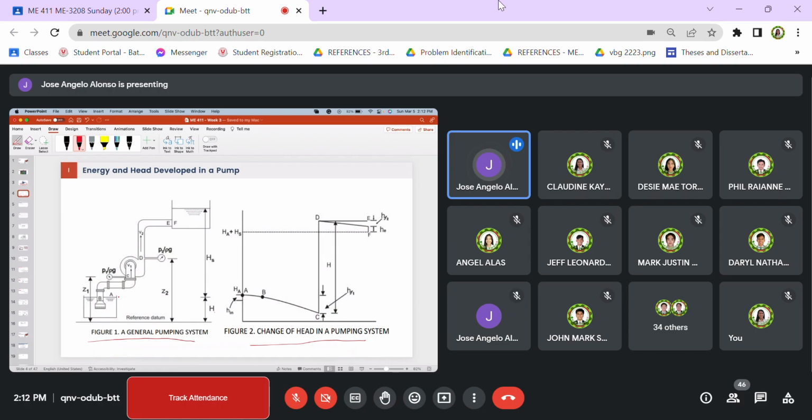So from the reservoir at level A, inverted triangle symbolizes elevation of the fluid. So before pumasok pa yung fluid natin papunta sa suction flange, dito sa part B, there will always be corresponding losses na kagad. So represented that by H sub in. So bumaba ang ating energy or bumaba yung energy ng fluid or yung head developed ng pump from A to B due to losses associated with or we can call that H sub E.